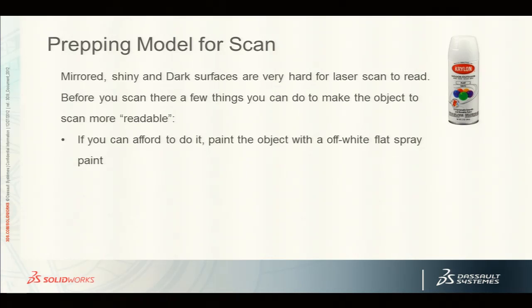Laser scanners love flat off-white surfaces. So if you can paint it, do it, and make it a flat white. If you can't afford to do that, and it's going to destroy the part, then you do have other alternatives.